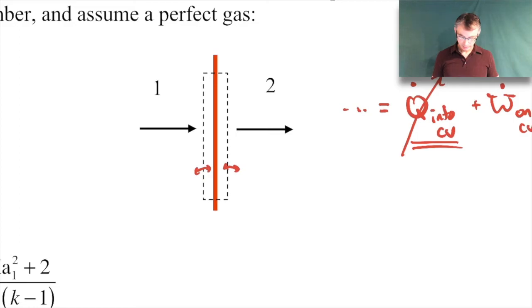So it's certainly isentropic conditions going across the dotted lines here, but through the shock wave itself, as I mentioned a moment ago, there are some large temperature gradients. The temperature from upstream to downstream can change considerably depending on the strength of the shock wave. In fact, the stronger the shock, the larger the temperature difference across it. And since this shock wave is very thin, you get large temperature gradients. Remember, temperature gradient is the change in temperature over change in distance. So the change in distance is very small, and you get large temperature changes. So it becomes a large temperature gradient.